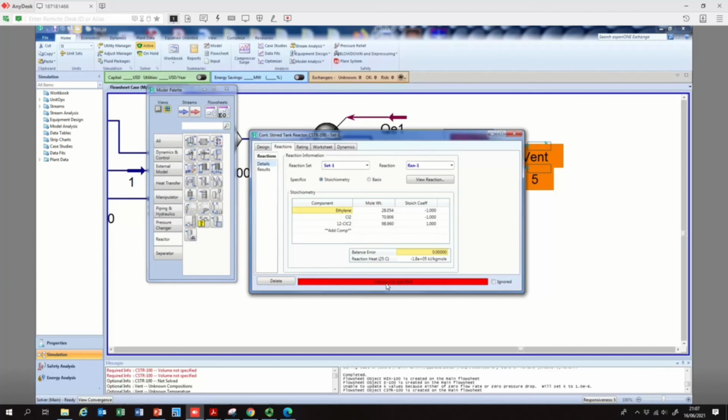So we have to define the volume, and still we are not sure about the percentage conversion. So we still have to dig into the literature for the values. If you go into the literature, you will find some information like, okay, your residence time should be a certain number of hours in order to ensure complete conversion of your reactants into products.